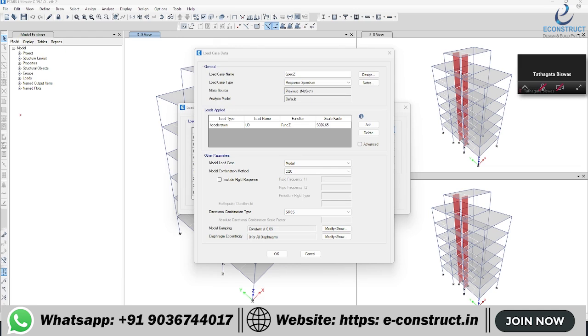Many consultants put a few parts here, and a few parts they put in the function. Or the entire part also you can put in the function. So there are two different methods of doing it. Once you are done with the scale factor, if you are taking the first method where everything goes in the function only, then here only the 9806 will come, which is the gravitational constant or G.